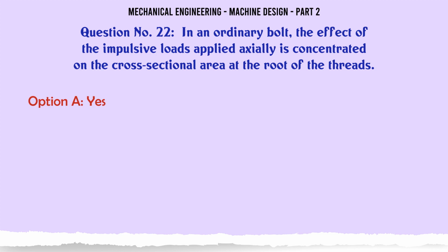In an ordinary bolt, the effect of the impulsive loads applied axially is concentrated on the cross-sectional area at the root of the threads. A. Yes. B. No. C. D. The correct answer is yes.